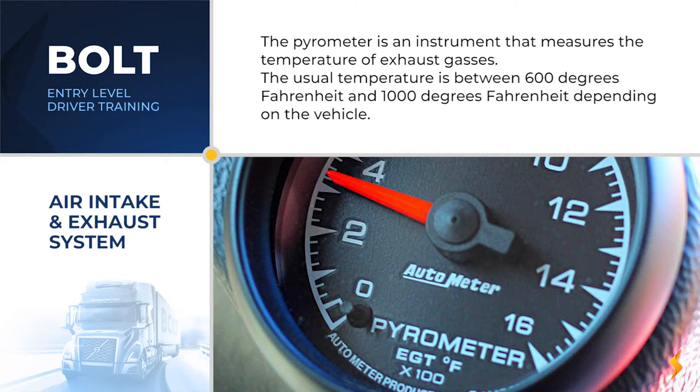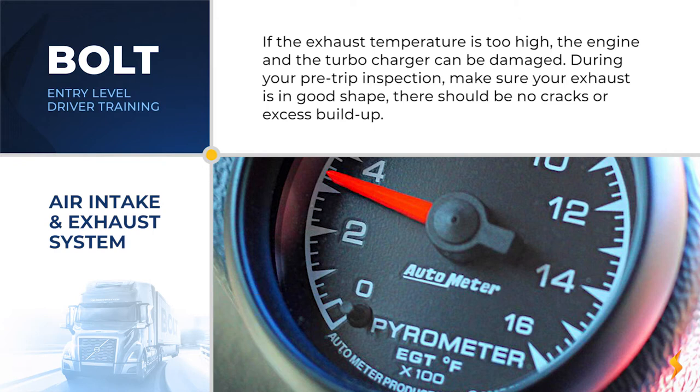The normal temperature is between 600 degrees Fahrenheit and 1000 degrees Fahrenheit, depending on the vehicle. If the exhaust temperature is too high, the engine and the turbocharger can be damaged. During your pre-trip inspection, make sure the exhaust is in good shape. There should be no cracks or excess soot buildup.